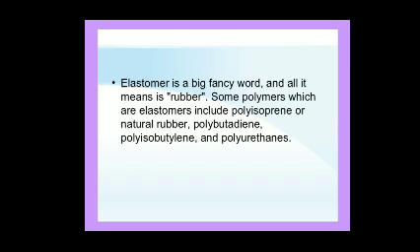These are examples of elastomers, which show elasticity. Elasticity means it stretches twice or thrice its original length, and when the stretching force is removed, it returns to its original shape. It is also one of the rubber characteristics, but it is made from man-made vulcanized rubber.